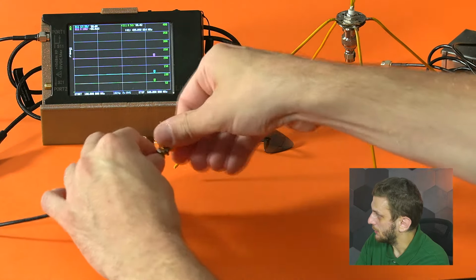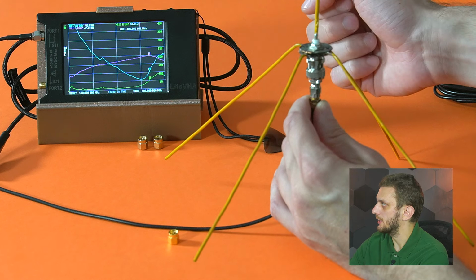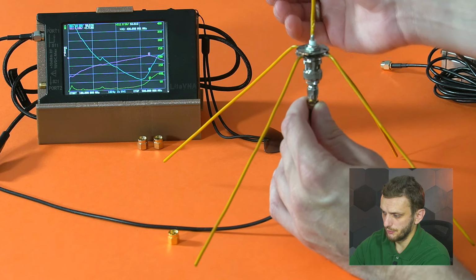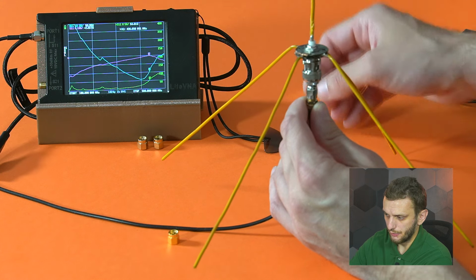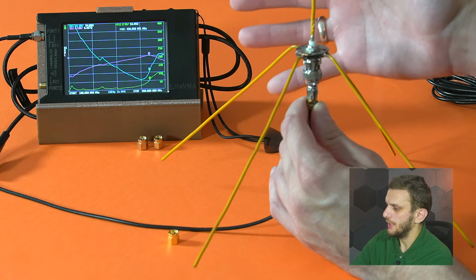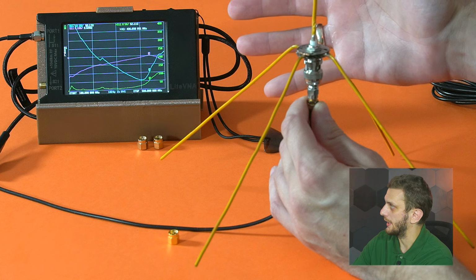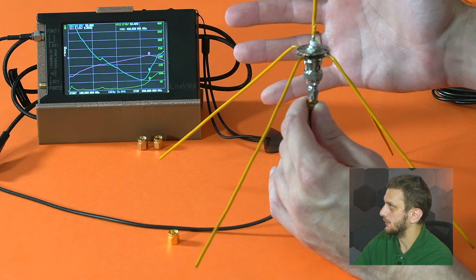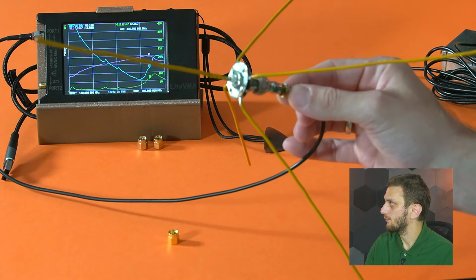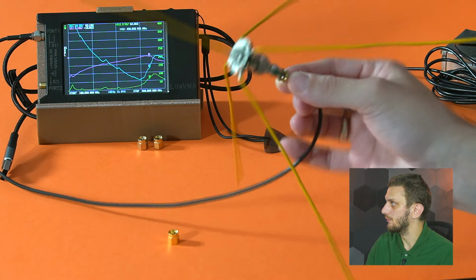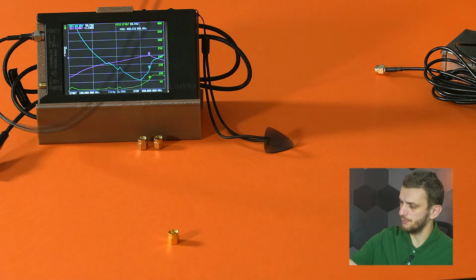If we connect it to the network analyzer, we can see that at around 436 MHz, it has around 53 ohms of resistance and 0.7 something milliohms of reactance, but the exact value will highly depend on what is around the antenna. So now if I have my hand closer to it, its reactance increases. If I hold it at a slight angle, again the response changes. If it's somewhere higher, again we're getting a different response.